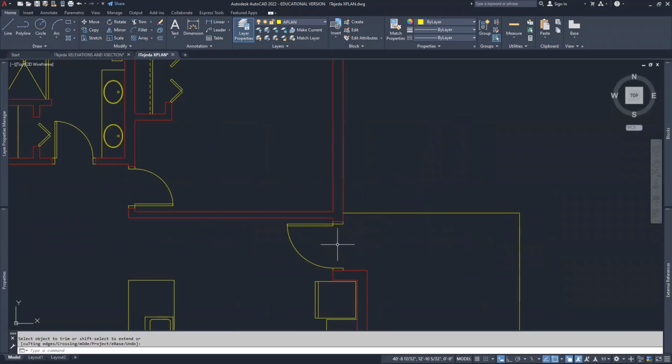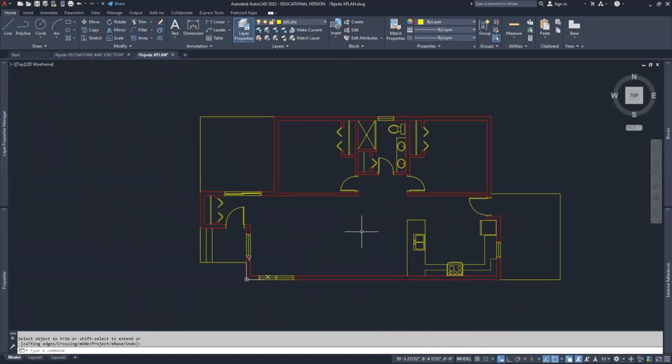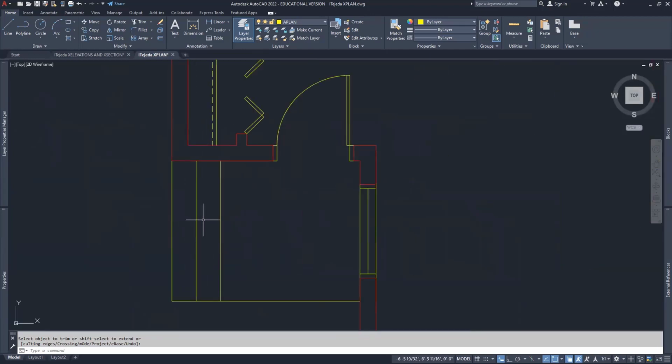Let's say over here, I would like to come out and then maybe go and step down. And remember, this building is only 18 inches above ground. I have over here 1, 2, 3 lines that represent the risers. And then I have these 2 steps. And then if I start down at ground here, that's at 0. I take the first step, that's plus 6 inches. I take the next step, that's plus 12 inches. And then one more, that puts me at plus 18.